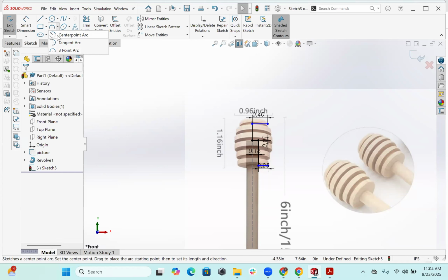So I usually use the 3-point arc. This you have basically control over the radius, even though you don't know where the center is. And you can kind of manipulate it like a spline. So if I get rid of these, pressing delete on my keyboard. Here's a 3-point arc. So start with the start point, end point, and then you can basically match your curve to whatever you want. This is a lot simpler arc to use out of all the three. And you can basically use it as a spline because it's harder to measure splines, but arcs are much easier.